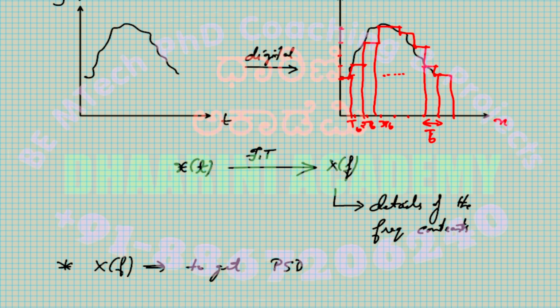digital radio channel. I want to cover an area of say 250 kilometers around my radio station. So I am transmitting at say 2000 megahertz. I want to cover this much area, which means I have to put at least this much power, sorry, not energy, at the frequency at which you transmit. This is the requirement. Power spectral density, spectrum means we know that it is a frequency plot. How much power is present at what frequency is very important.